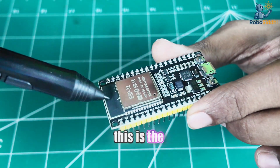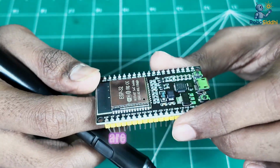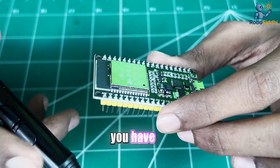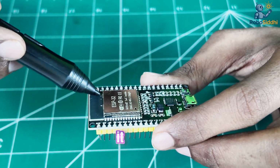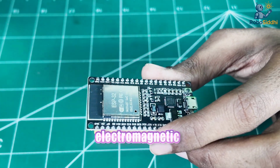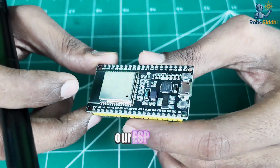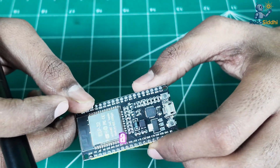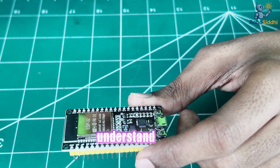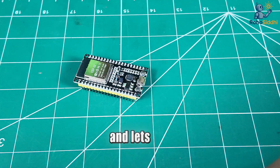One more thing, this is the antenna of our ESP32. So whenever you are going to make projects and whenever you are going to use a metal casing or metal shielding, you have to keep in mind that you keep it open so it can communicate, it can send EM signals, electromagnetic signals, outside the box. So that's how the ESP32 is there, and this is our ESP32 board. Now let's take a look at our GPIO pins, and let's understand how they work more closely. So I have made slides for that. So let's go and see how it works.